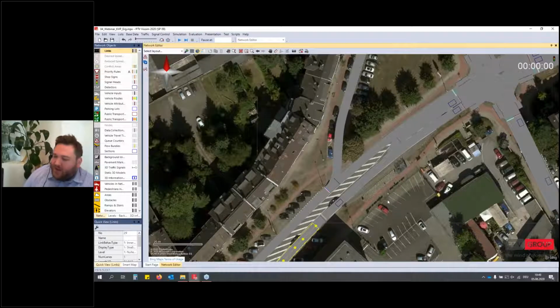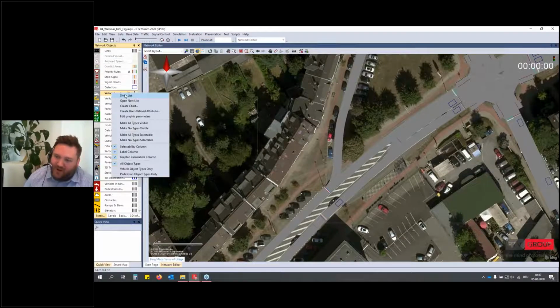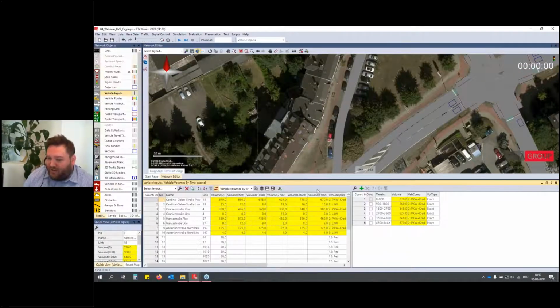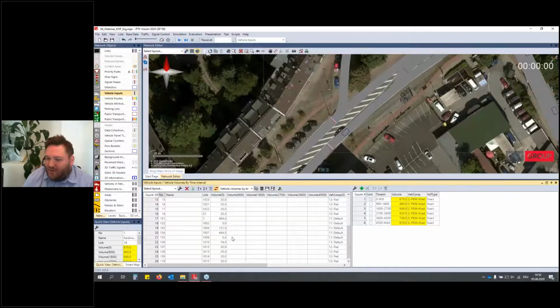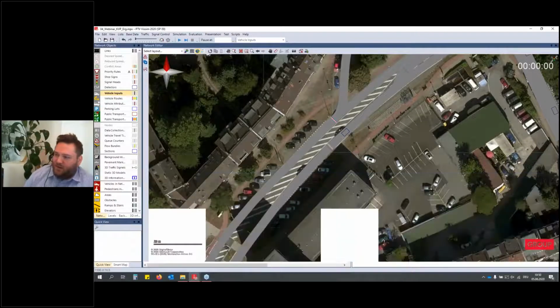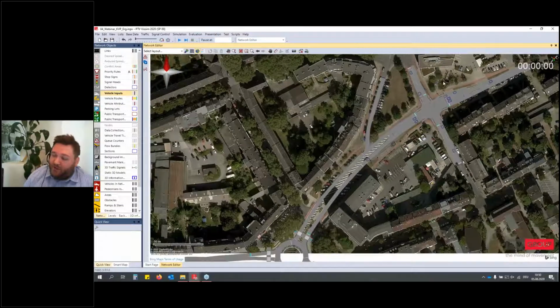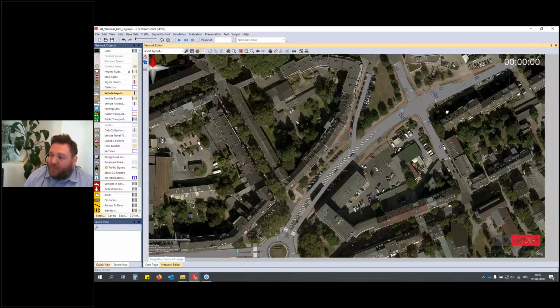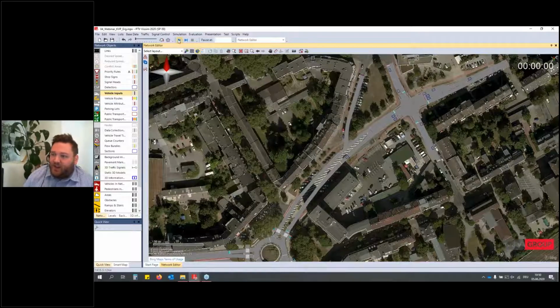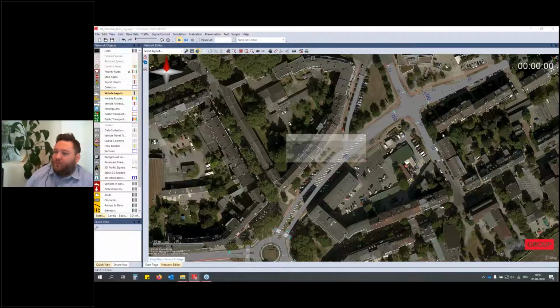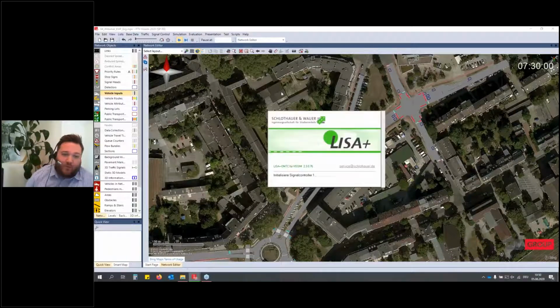One important thing now is that we delete this vehicle input as well as the vehicle input for the other direction, simply because if we simulate this model without deleting the input, we would have double the traffic in the model that we should have. So all measurements and all evaluation elements, with all definitions, are already implemented in this model now. And with that, we can simply simulate both our junctions in context of the wider network.